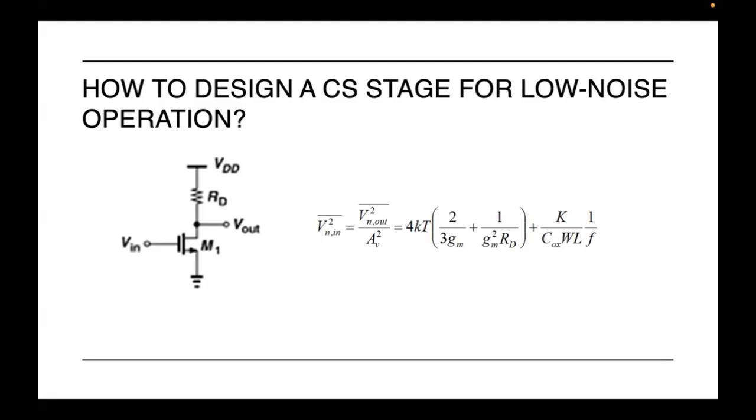So in these ultra low threshold voltage transistors, we should expect a high white noise. Alternatively, when you go to gain stages with high GM, then you should expect relatively low noise.